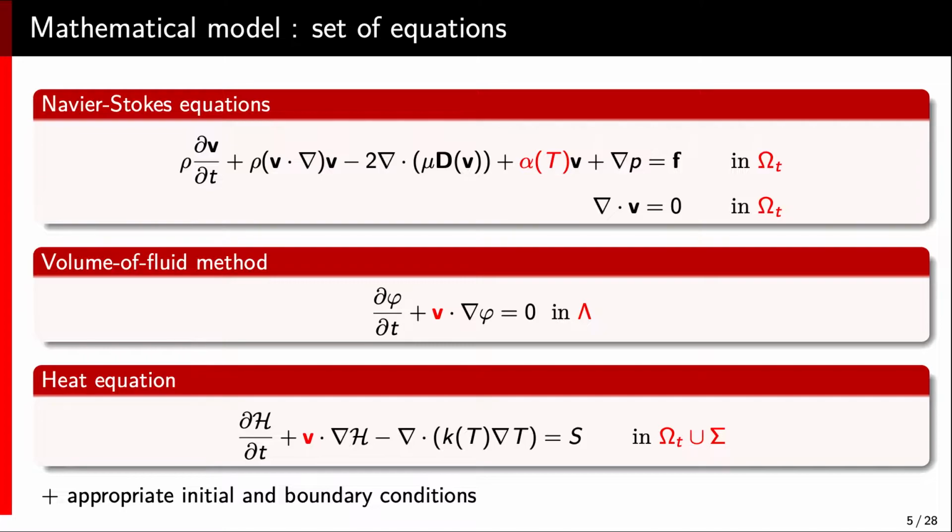So now we have our variables, we need our equations. First, we have the equations for the incompressible fluid flow, and we are going to consider the Navier-Stokes equation, or the first box here, with the additional reaction term, that is the coupling with Darcy, that will allow us to penalize the velocity in the solidified metal. And this will be solved in the so-called omega t. And omega t is the domain, but zoomed on the smaller domain, on the smaller box.